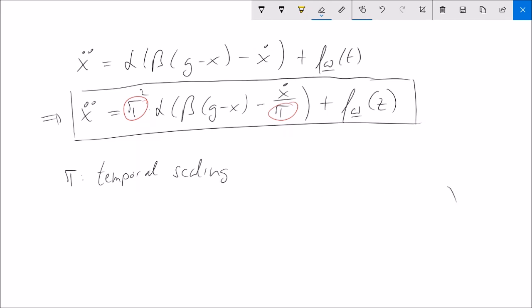I will simply delete that. And now we are nearly done. What is simply left is to define this forcing function. And this forcing function f, dependent on the weighting parameters w, is generated or defined through normalized basis functions and is, as I mentioned, dependent on these weights, which we have then to learn by examples, basis functions.